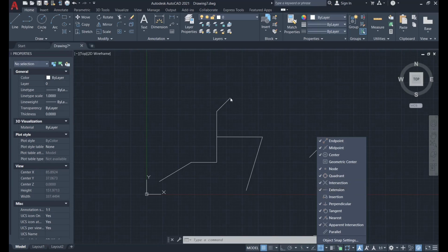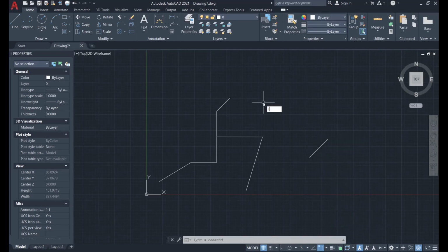It will show you the extension of the line. So if I go back to the line command and place the cursor here, it must show me the extension of the line. Let me place the first point. As you may see, now we also have a green line over my line, and it also snaps in place.